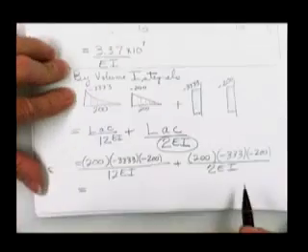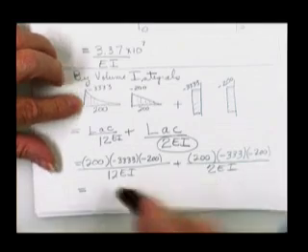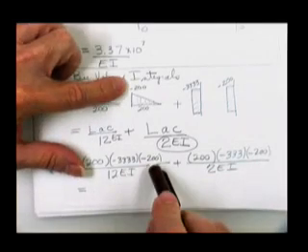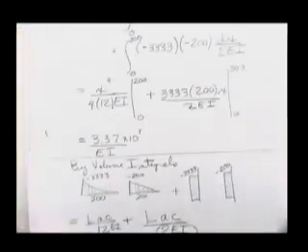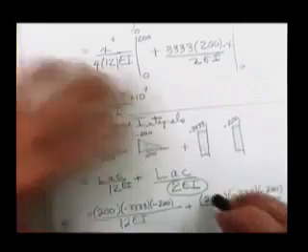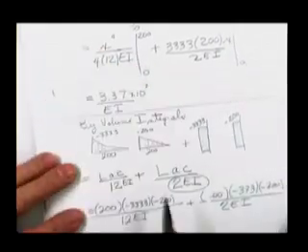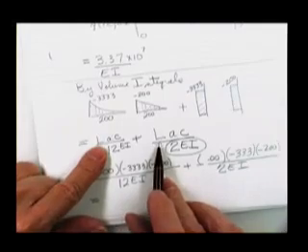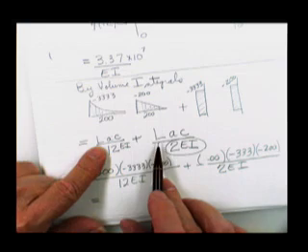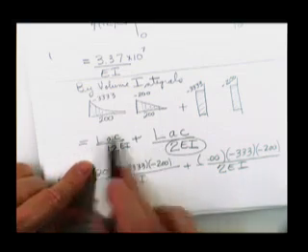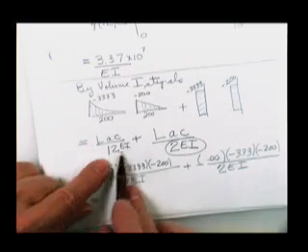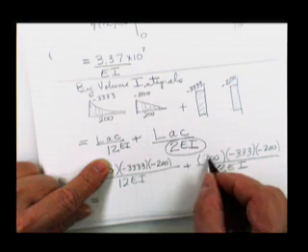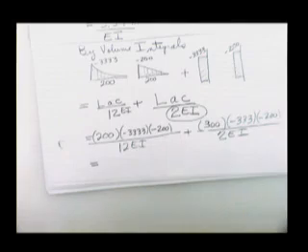We got a 3333 and a 200. The length was 300. It says L. There's a good way to get in trouble. Well, they all say L. So I just put 200 everywhere, and that's not going to work. It has to be individualized for that member, including its length personally and its EI personally. So no question about it, those are really nice for solving for these things.